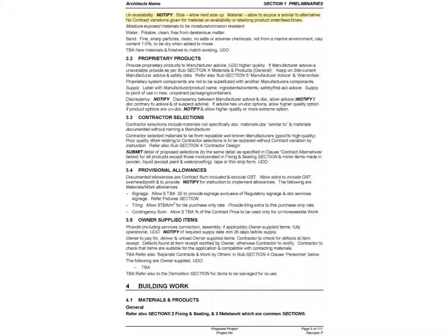There are many other safety features in the spec. Another two quick examples are in section 18 linings. If ceiling lining framing is not documented, this does happen. First notify, then allow for a proprietary suspended ceiling system. Also, items to be architect confirmed on site, e.g. ceiling hatch locations, the contractor instigates this process by notifying for an instruction.